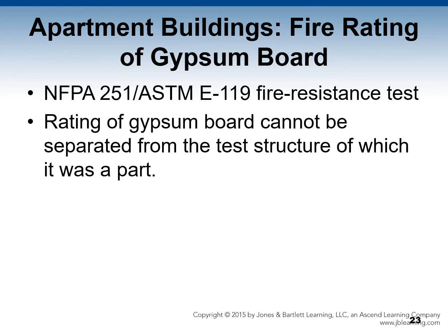A myth: gypsum board possesses the magical ability to limit the extension of fire. I've said in previous chapters and in other classes, eventually everything's going to burn, given the right circumstances and temperatures. So the rating of gypsum board cannot be separated from the test structure of which it was a part. So it's only as good as the test structure